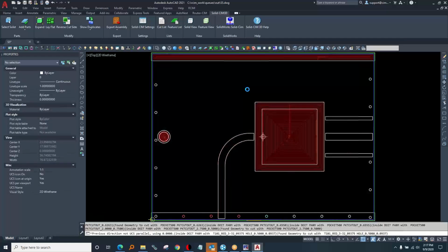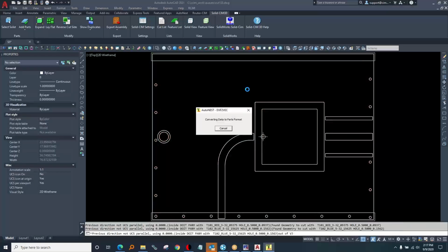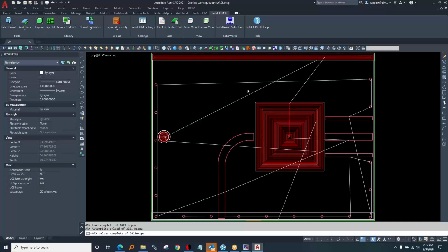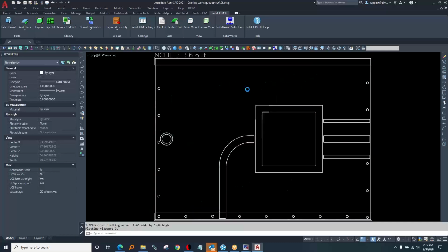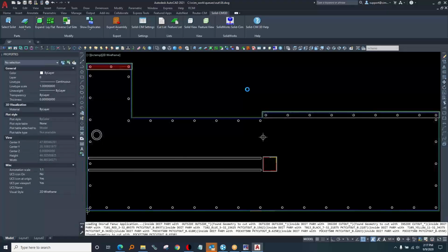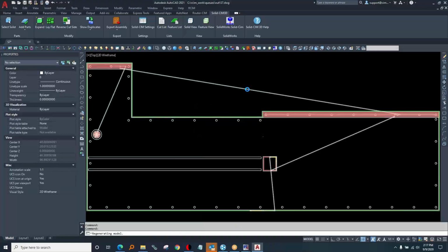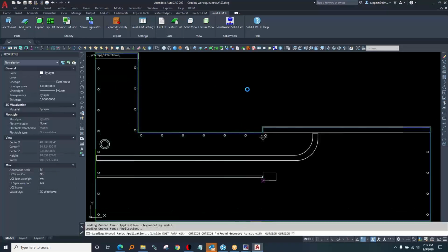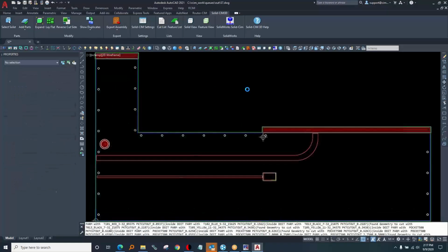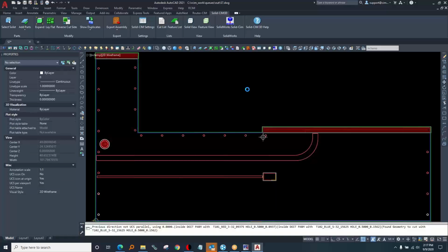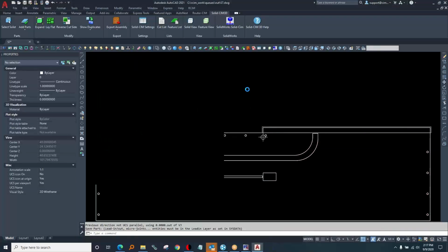A lot of these parts have machining on both sides. So we're going to do what's called two-sided nesting, where you'll put the sheet on the table upside down. It'll do all the marking and the machining for the back side. It trims the edge of the sheet, so when you flip it over, it's a machined edge that matches up the parts again. And then it'll do the front side operation.